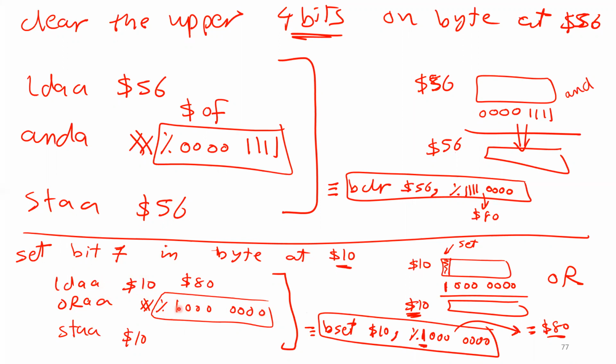This is exactly what happened, as I told you before in one lab, right? It's very tricky, because you have many zeros, and sometimes your eyes cannot catch it, especially if the program is long. That's why hexadecimal is usually better. But if you want to use binary, I'm okay with it, but you have to be careful to avoid making mistakes. So this is the number I'm going to put here, and after that, I'm going to return the value back to number 10. So load, OR, store. Any question? Okay, so this is one idea to do it.